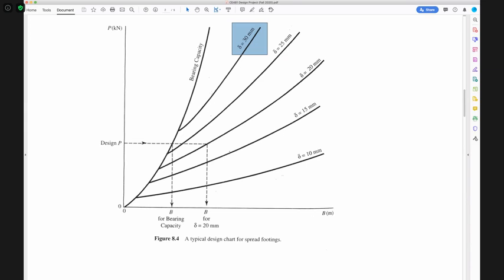For instance, you have a dummy load and it produces your calculations and so on. You get a delta sigma and all the Schmertmann stuff and so on. And then a settlement's going to show up somewhere else in your spreadsheet. And you can iterate that by hand. Just keep changing the load until you reach exactly the right combination of load, size, and settlement that results.